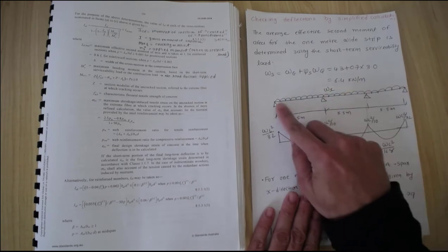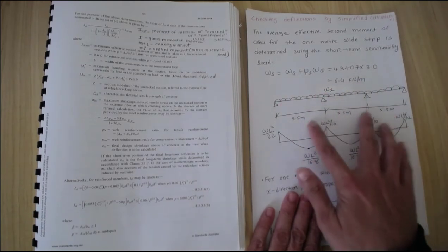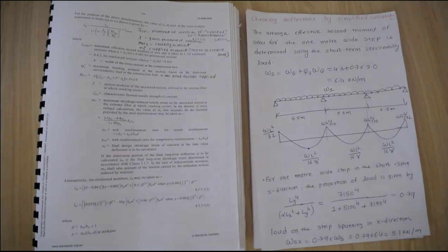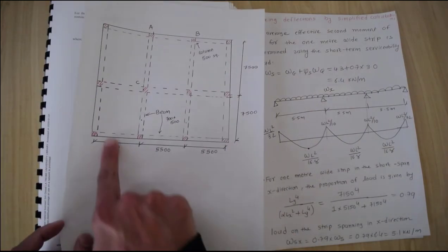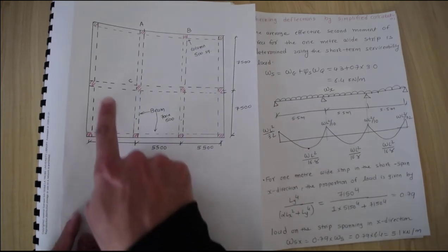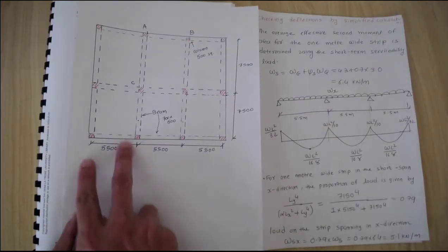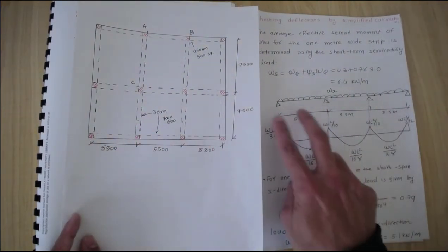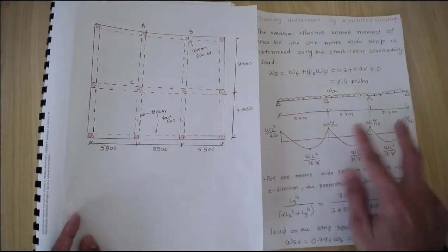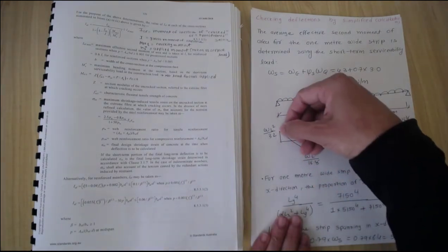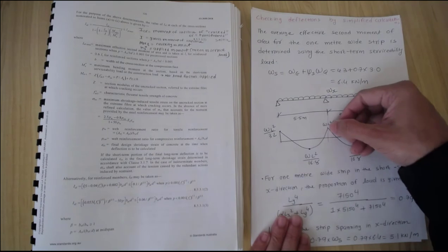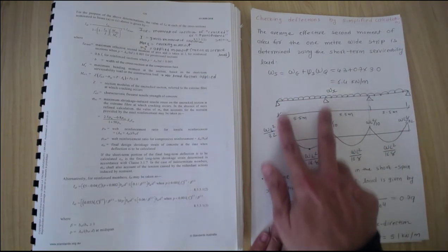Now this 6.4 kilonewton per meter does not come onto this strip. How do I draw this strip? If I take you back to the figures here, for this strip I draw, let's say, a 1 meter wide strip for the slab. So this is the slab, a 1 meter wide strip, and these are the supports. You can consider these the supports of the beam, and they are 5.5 meters apart. If you do the structural analysis on this example, you would see this kind of bending moment, negative bending moment at the support, positive and negative bending moments. We are interested in this zone only. As you can see, we are working on this corner slab.